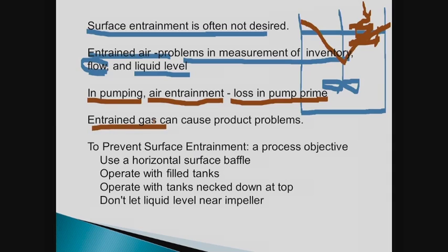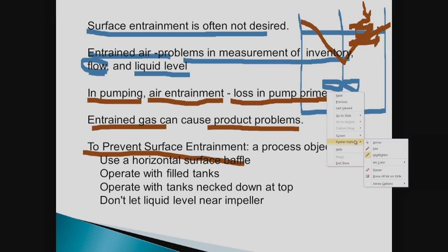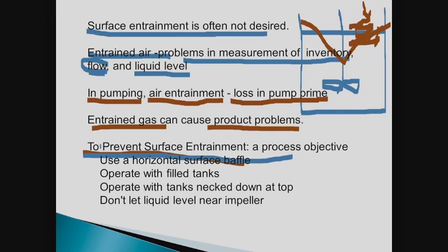Entrained gas, or entrained air in particular, has oxygen in it, and oxygen is a bad actor, and it could cause product problems. If you aerate your material, the performance of aerated material could be quite different than the performance of non-aerated material. Now then, you may wish to prevent, I like the blue better, don't you? Let's go blue. You might wish to prevent air entrainment, or surface entrainment, excuse me.